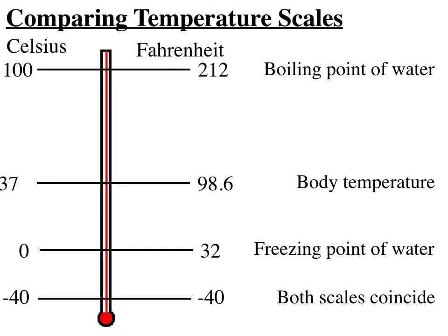You just get some water and freeze it, and at atmospheric pressure, mark off a mercury column, call that 0, then get the water and boil it against atmospheric pressure. The liquid in the thermometers expands, and when the water is boiling, you mark it off again, set that at 100, then divide it up into 100 graduations, or make it centigrade.